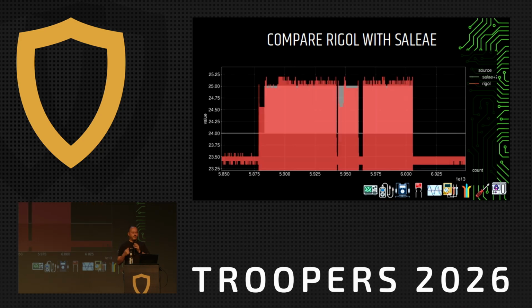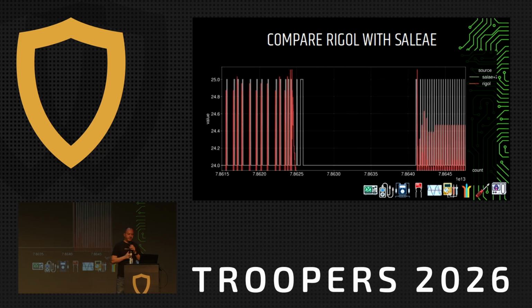Well, let's zoom in. If we zoom in, it kind of looks good, but we see that there's this half level in red at the very beginning for the oscilloscope. If you zoom in even more at the symbol level, we see that it isn't that good anymore, right? So we see that Rigol stops capturing data a bit faster, and then it begins capturing it a bit later.